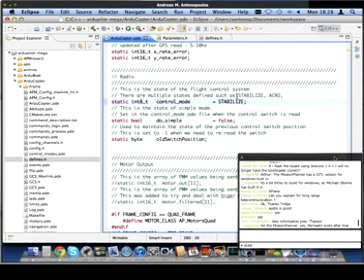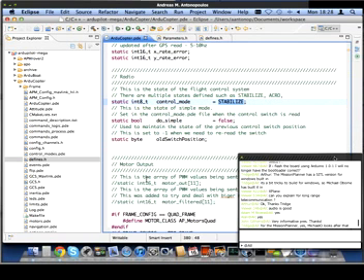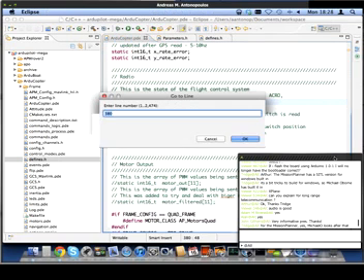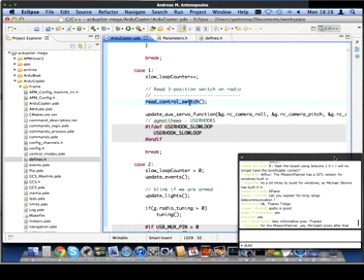Then what happens is, if you go into ArduCopter around line 380 or so, you'll see that there is a control mode variable, and that is where the current flight mode is held. All through the code, you'll find that it looks at the control mode. The way that control mode gets updated is in ArduCopter.pde line 1329. You'll see that it's calling this read control switch.